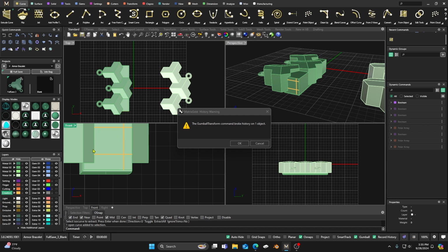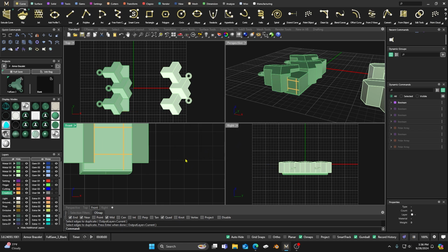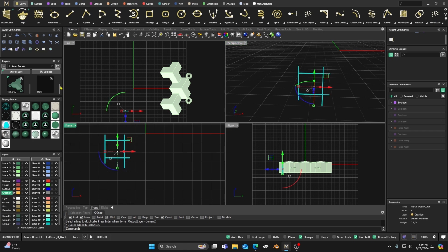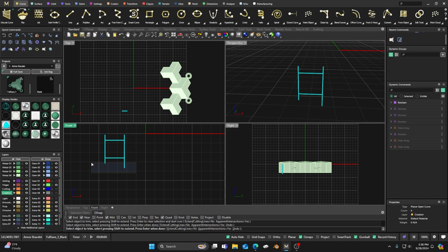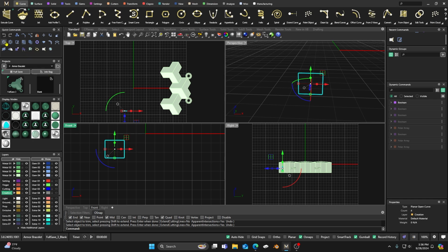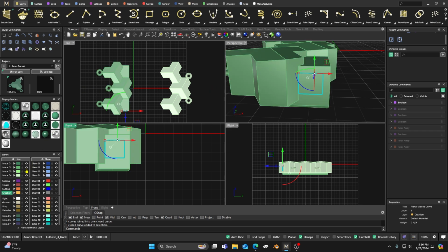So now you can see we're starting to get that box, right? And then again, we're just going to do right this edge here and then hit enter, and I'll just leave that one there. I think that one's probably okay. Yeah, maybe okay. So now let's just go ahead and hide that surface there. We'll just grab all this and we will trim, right? So let's trim this, trim these two here. Click accept that and then join those together. And to tell you the truth, I'm just going to take it, well, it doesn't matter. Yeah, okay, we'll just leave it there.